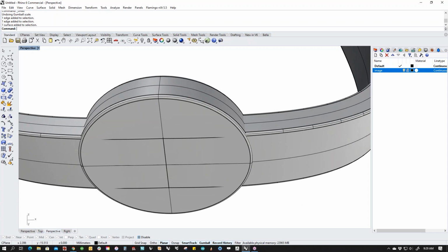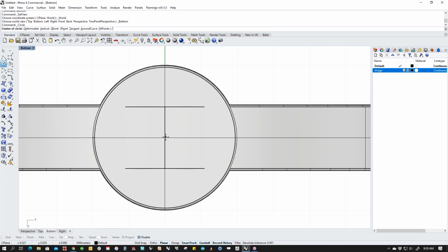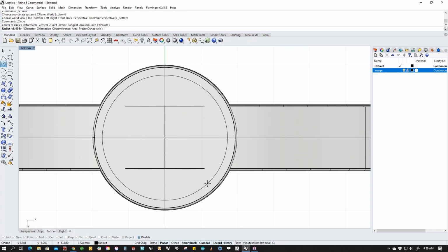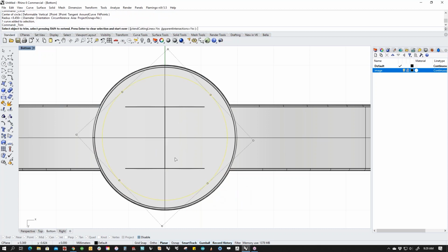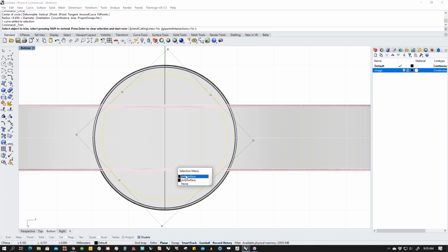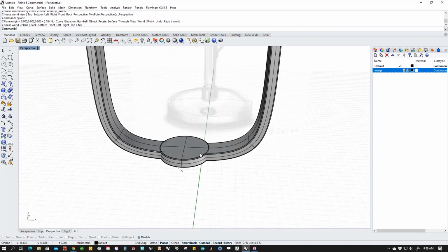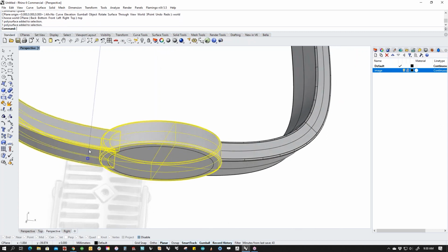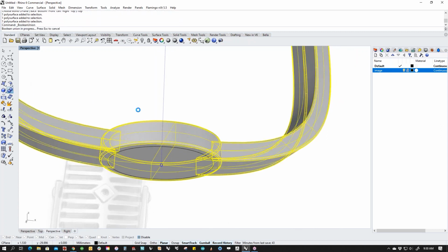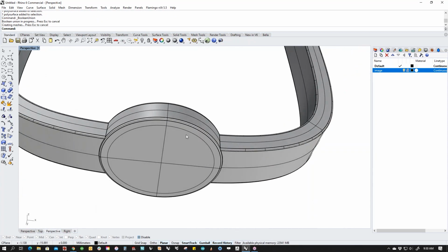Now, if I didn't want to scale, I could probably, let's go to the bottom view, I could probably hack this out like this. And I could probably trim that entire section out, which gives me a much cleaner intersection. Now let's see if that alone will fix it. I'm guessing, but let's see. And in that case, it did. So that was the problem.